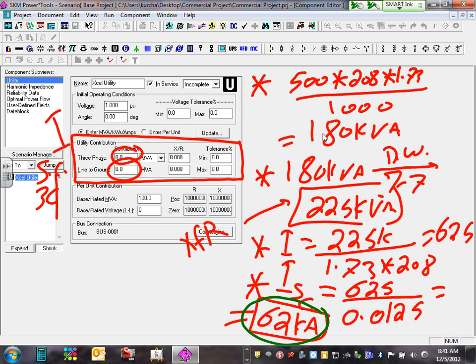Okay? All this to come up with this number. Now, this number here, first I have to change this one into amps, and then I have to put right here 62, I think it's 62 kiloamps. For the low voltage, for the line to ground, typically we use half of this. So line to line, 62, line to ground, what's half of 62? 31 kiloamps. Done, gentlemen.